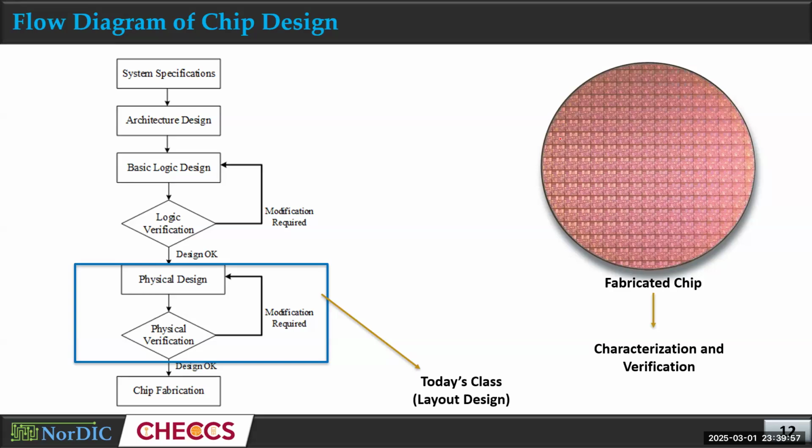So when you get this chip back, the next step is again verification. We use that probe station that we showed you, and we place these chips inside it. We apply the inputs. For example, if we have an inverter circuit, we will apply a pulse of logic 0 and logic 1. That will be our input. And we will measure the output, whether for logic 0 we are getting logic 1 or not, and for logic 1 input, whether we are getting logic 0 or not. So that's what we do. We apply inputs and we measure the outputs.